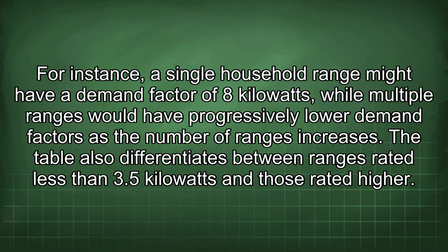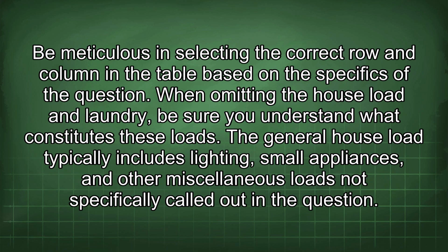The table also differentiates between ranges rated less than 3.5 kilowatts and those rated higher. Be meticulous in selecting the correct row and column in the table based on the specifics of the question. When omitting the house load and laundry, be sure you understand what constitutes these loads.